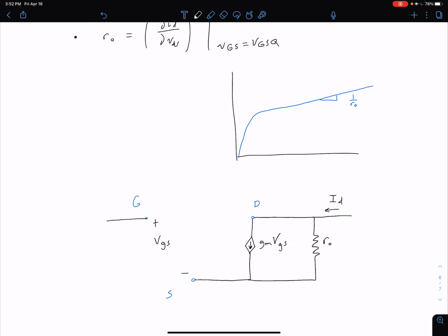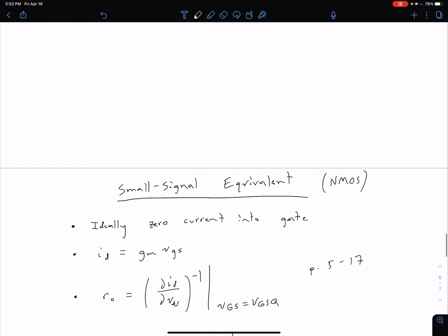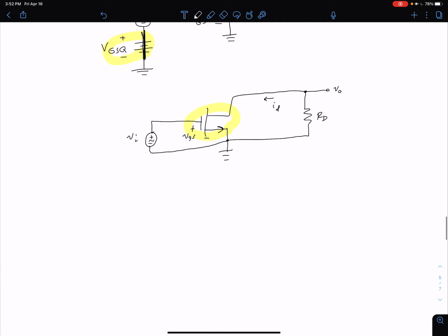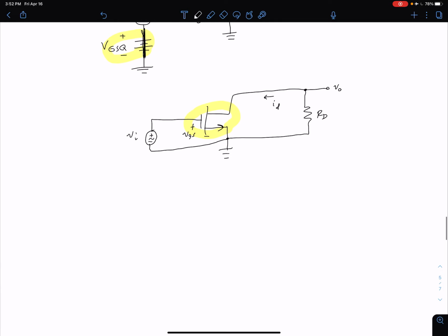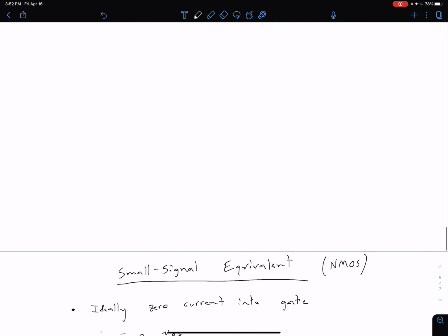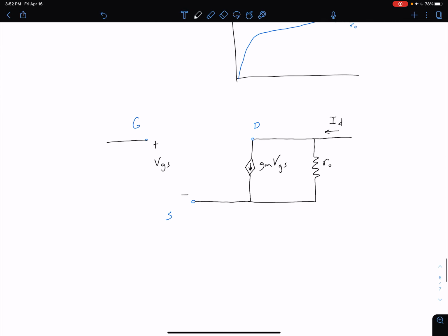So now what we would want to do is just sort of connect that to our circuit up here. And so we could see that our source, of course, is at ground, and our VI is connected between our gate and ground. So coming back down here, all we would have to do is add in our VI over here. So again, switching to phasor notation, capital V, lowercase i, that's connected between our gate and source, where our source is grounded.